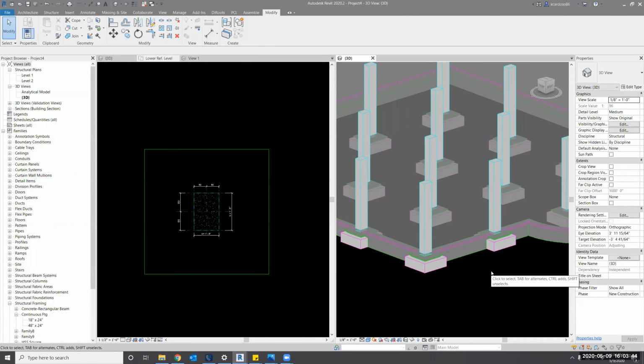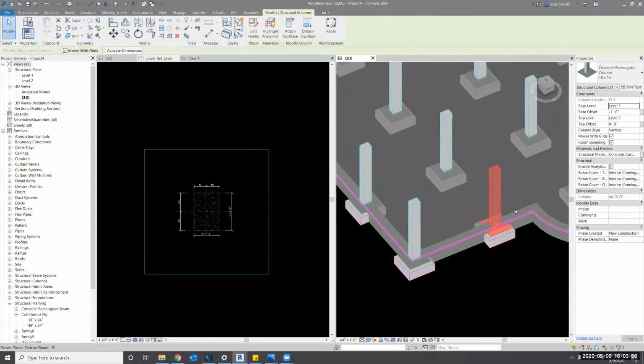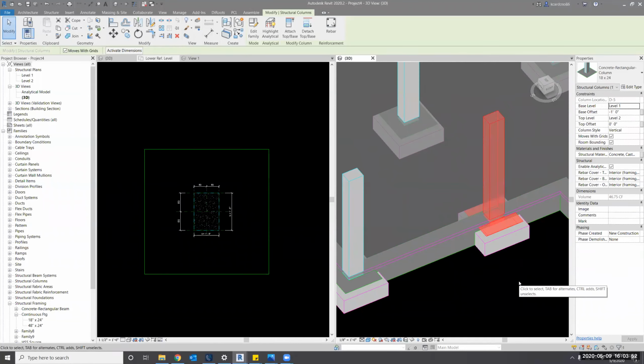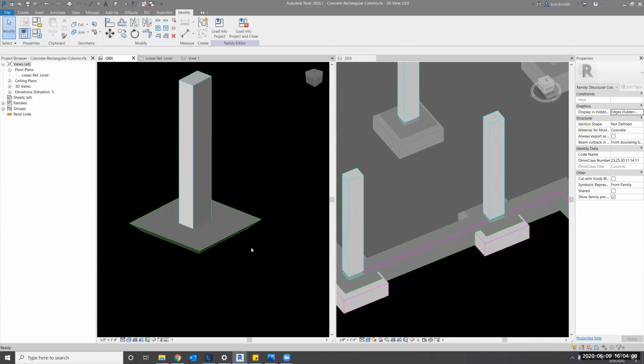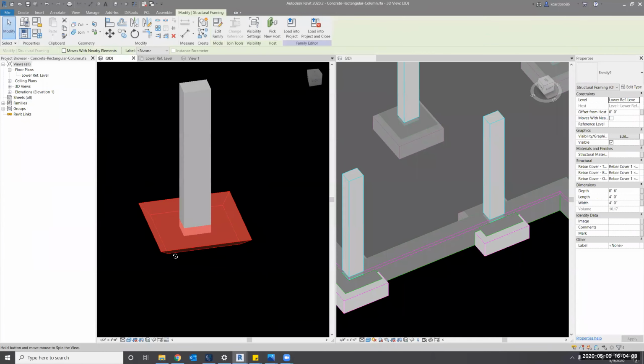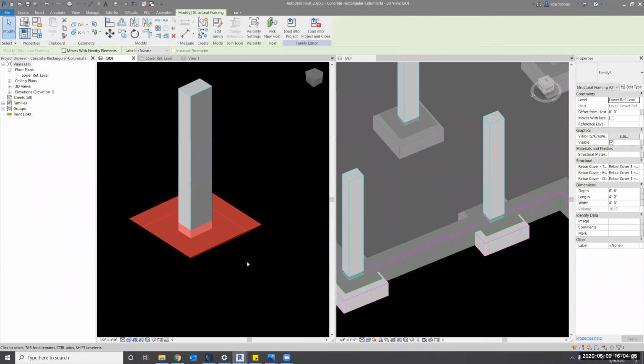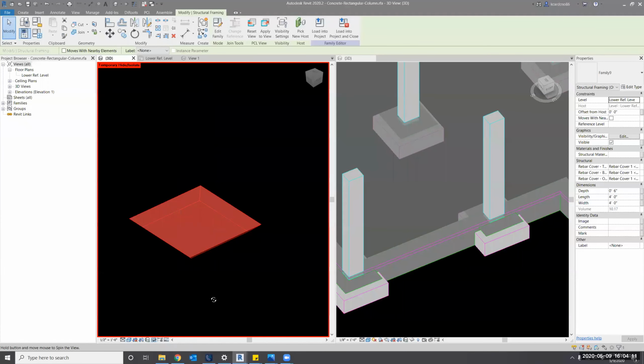Let's start adding some functionality to this thickening. We don't want just this default geometry. We want to be able to modify it. And if you look close enough in your 3D of your family, let's type in 3D here. Well, I'm technically still getting incorrect reporting. If I select this family and go to the temporary hide isolate and isolate it, there's no void there for my column to punch through. We know that verticals go before this piece of concrete. So let's go ahead and add that void in the family.